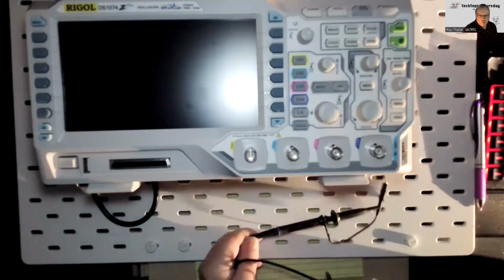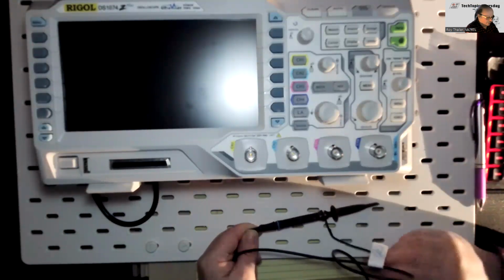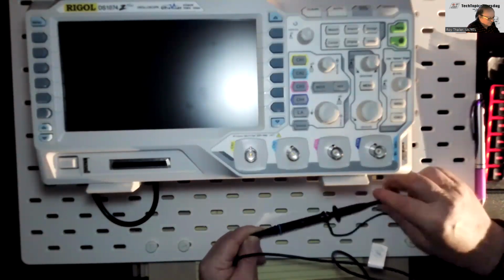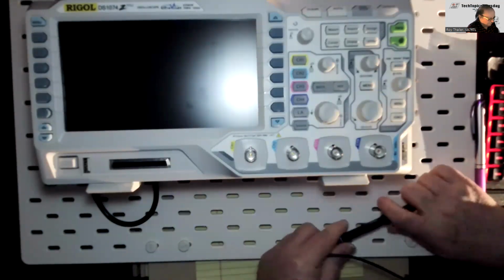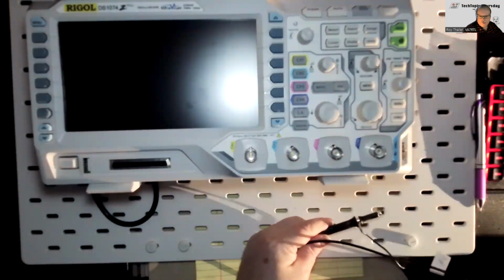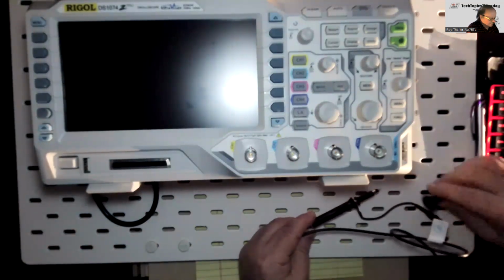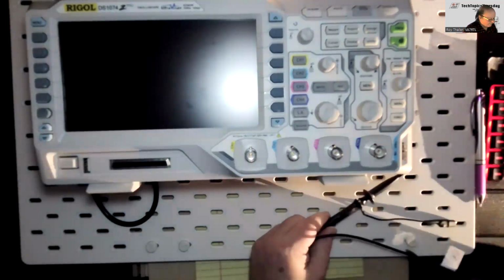The other end of the probe looks like this. This is your ground, so make sure you always connect this part to the ground of what you're measuring. Then this goes to where you want to measure the signal. Here it has a little clip. You can pull this off and you get a point that you can touch to a circuit to test it. When you're going to high frequencies, this length of lead is going to present a problem, because it's going to interact.